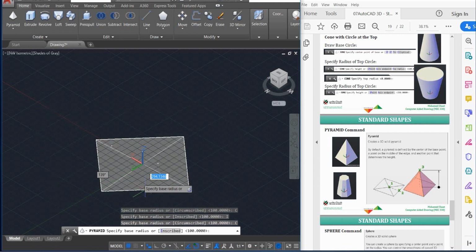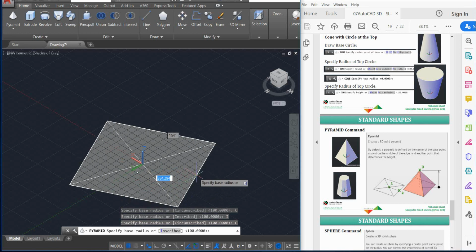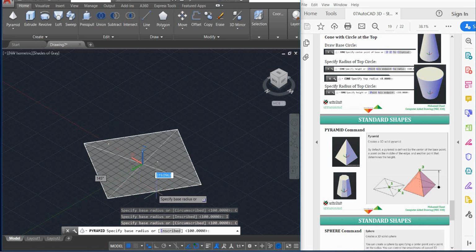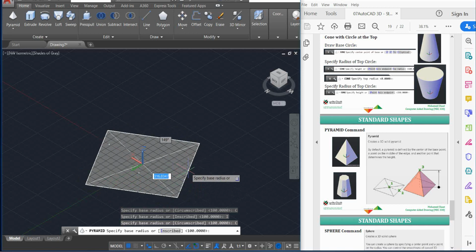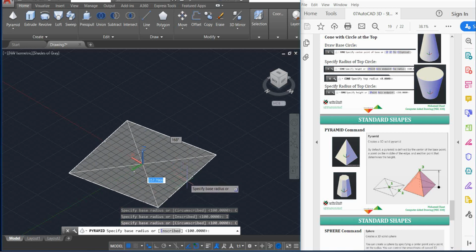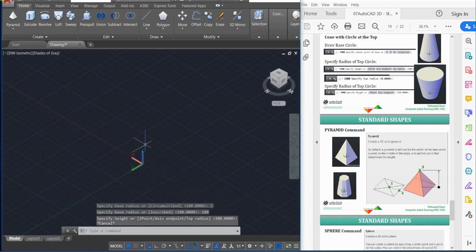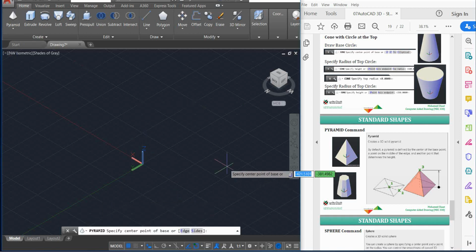Then your objective is just to specify the base radius, how much it is, like you're drawing a circle. But remember that you have to keep the base oriented. As you can see, there is an angle that changes here. You can tap on it and specify the angle, let's say 180 degrees. So you are giving rotation to the base with 180 degrees. Then you're gonna specify and click. I clicked on it, so I'm just gonna repeat it from 0,0.